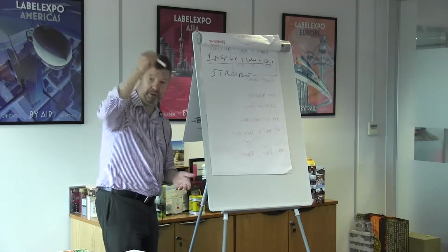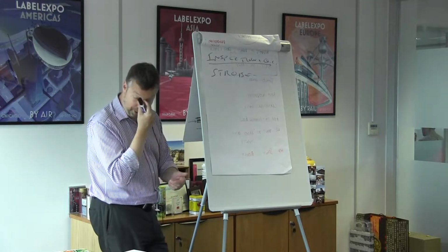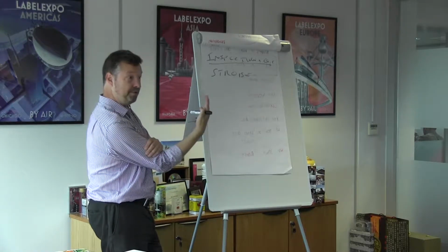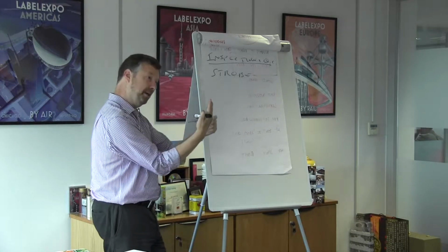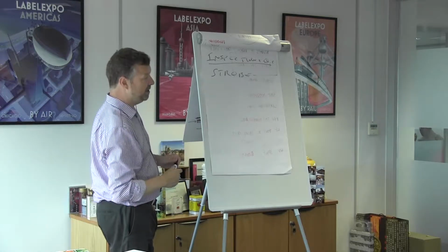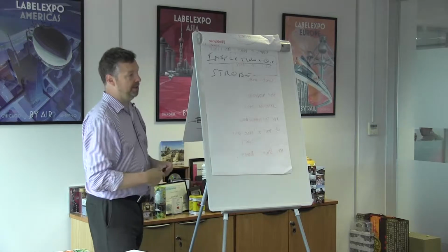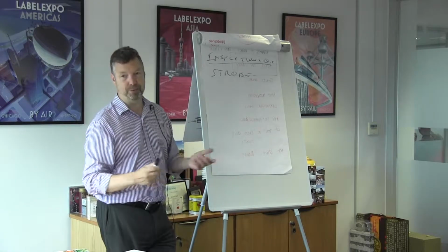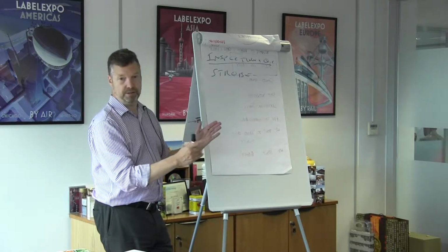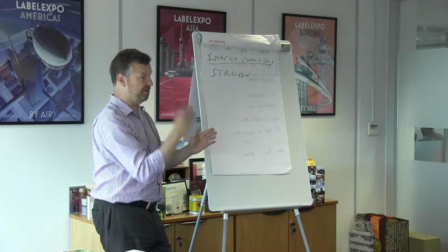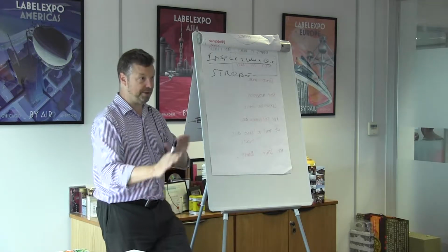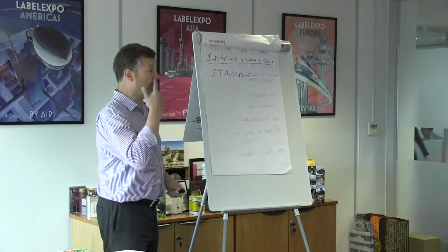So the strobe light shines on it, exactly like in the Michael Jackson thing going on, and what the operator sees looks like just an image standing still, but actually it's sampling that image as it comes through. That means the operator can now just look at that, and they can see if anything's starting to go wrong. Let's say the web is running 120 meters a minute, they'll be seeing an image every 2 meters. Then they start to see that something's going wrong, the colour's going wrong, or digits been missed out, something's happening. So that's the old kind of manual inspection.